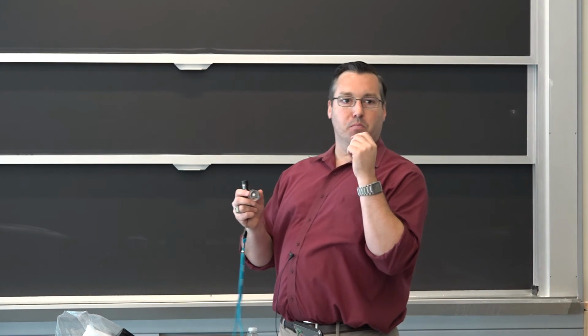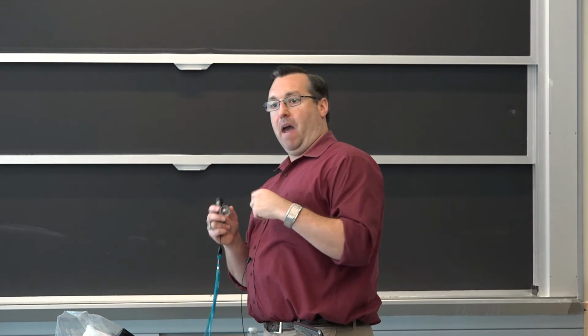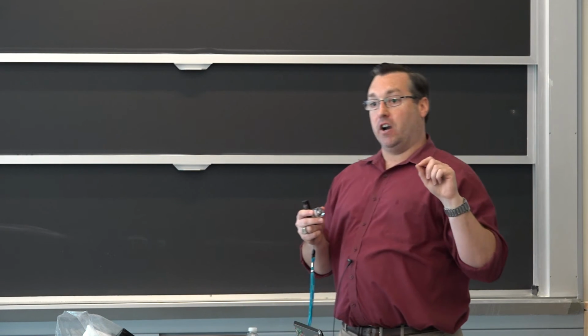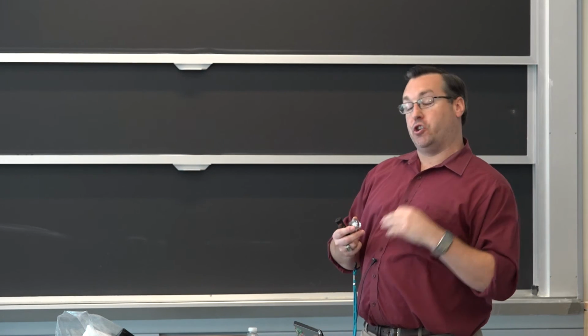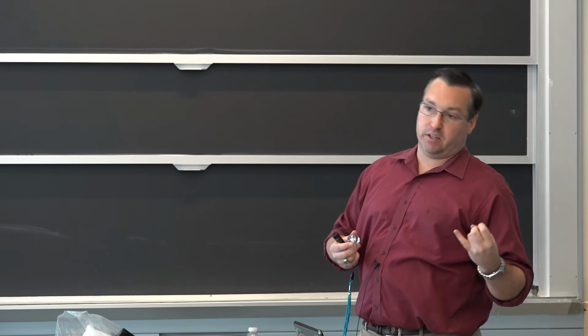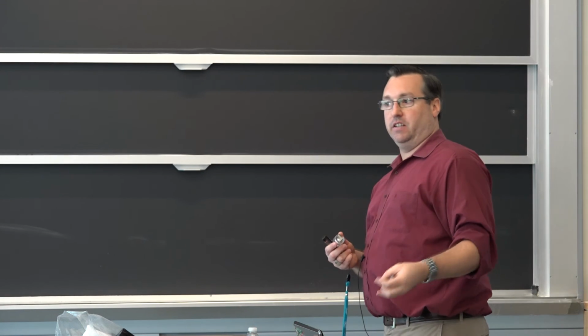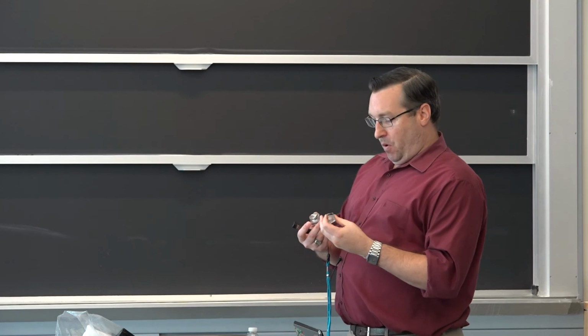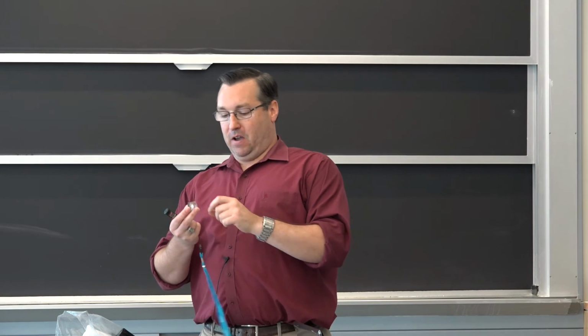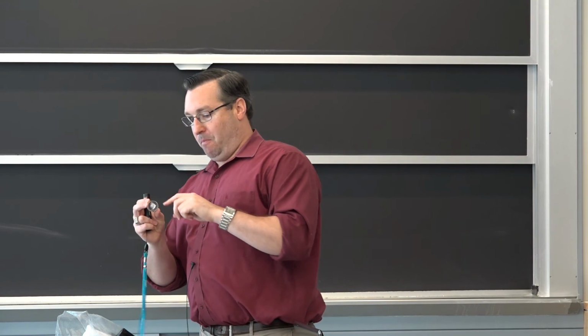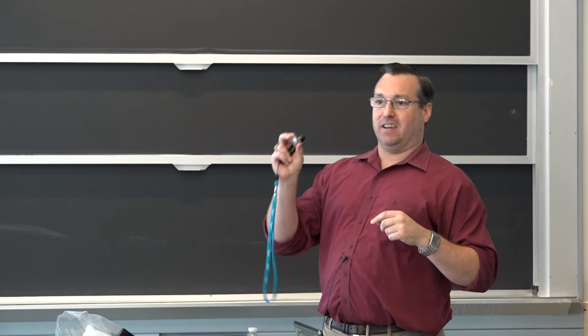So you can also do micro hardness tests versus macro hardness to see if the hardness is in line with what it should be, and that will tie into your heat treating of the material, annealing, things like that. But one of the other things to note is actually I use these to show what not to do when you're making the mount.